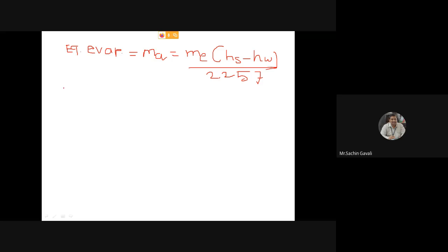HS is equal to HF plus X into HFG. This HF and HFG we have to record at, say, 7.5 bar.